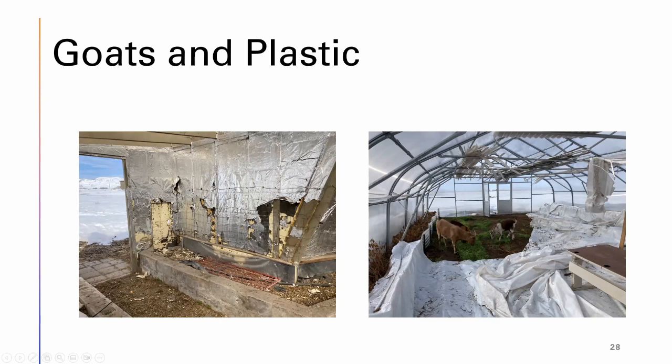So what you could do, if you use blue boards, polystyrene white boards or the yellow polyiso, is layer it up in 1 inch layers so you can match the curvature. Put on whatever surface finish you want: paint it white, put on the aluminum foil, whatever you want. You'll reflect the light back. Put your IBCs, your intermediate bulk containers, down at the base of that wall and paint those black. You'll have a very well insulated north side, and your ratio between your glazing surface and your growing surface will be very low, meaning you lose very little energy. You'll have good thermal mass in the IBCs, so through convective heat transfer through the night, they'll release a lot of energy.